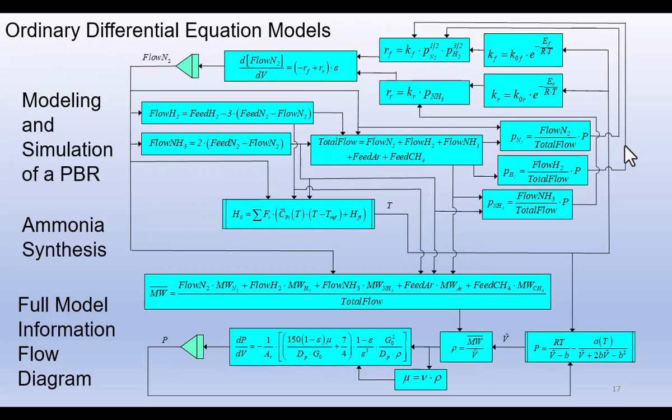In this case, we have two differential equations, one in terms of our flow, just of nitrogen, just as before, and another which solves the Ergun equation to provide the pressure, so that the full model allows the pressure to vary as the flow goes through the reactor, and due to friction, the pressure actually reduces somewhat.